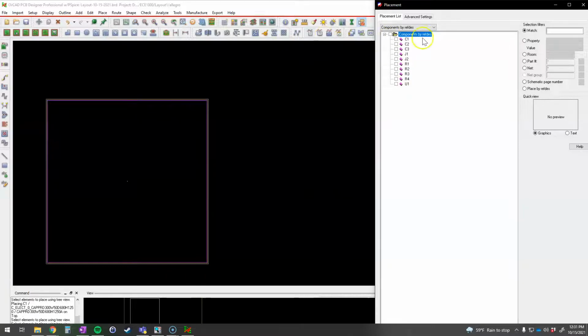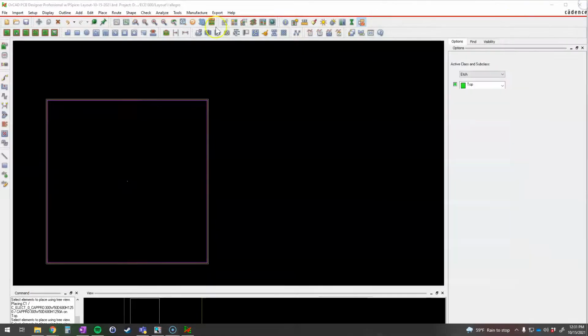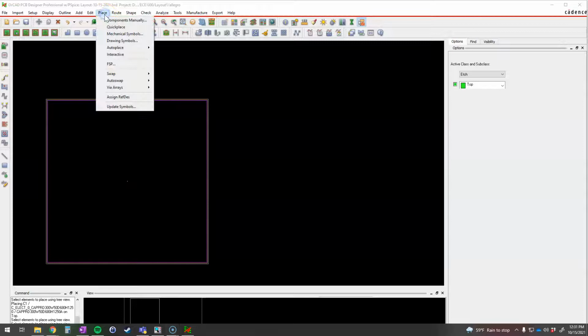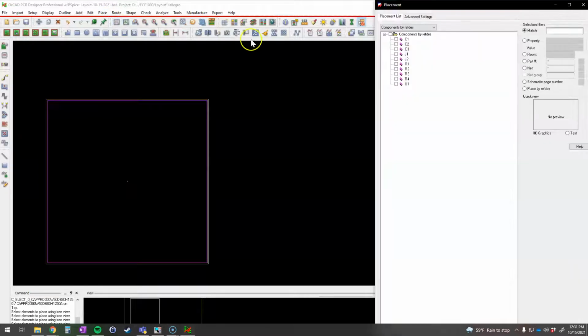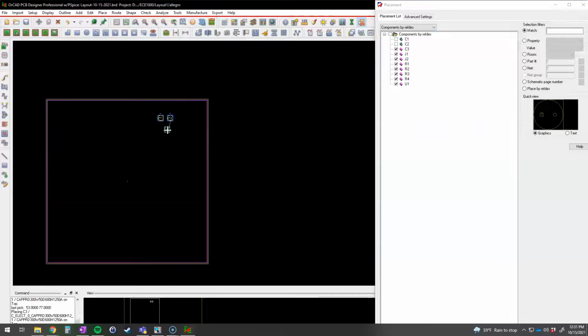And then here I'll just exit out of this, just to remind you, I went to place components manually, and then I select all, and you can kind of see some of the pictures there. Now you can see there's plenty of room to put them in the board. Again, sometimes people put them outside the board. I'll just randomly put them in the board for now. And now I created a board that is obsessively large at this point, way larger than we need.